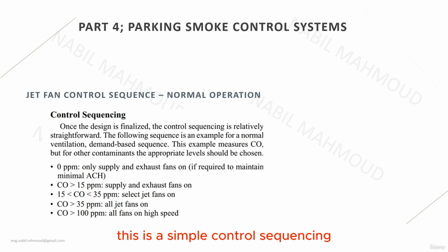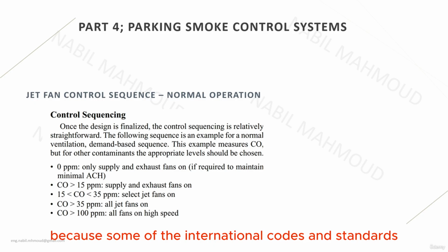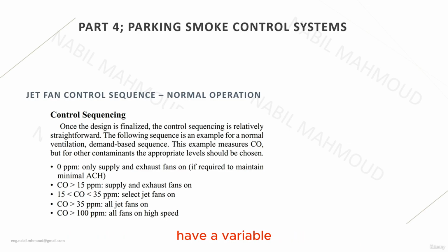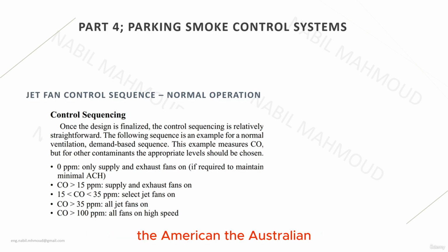This is a simple control sequencing that is followed by the majority of operation scenarios. However, in order to specify the exact sequencing required, because some international codes and standards have a variable allowable limit for carbon monoxide, you should refer to the authority having jurisdiction regulations and to the related international codes and standards that you follow. The British, the American, the Australian, some of these codes are slightly different from each other.